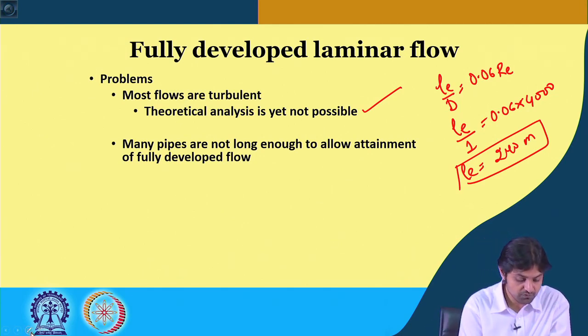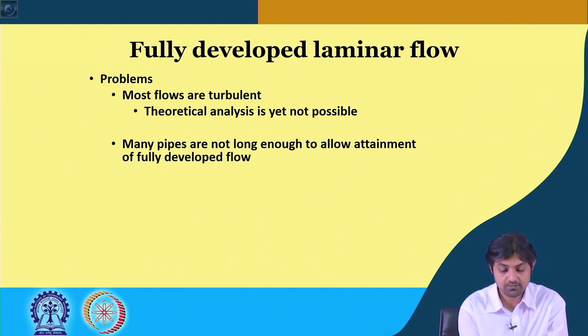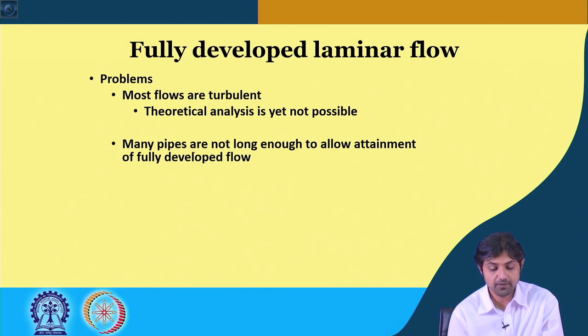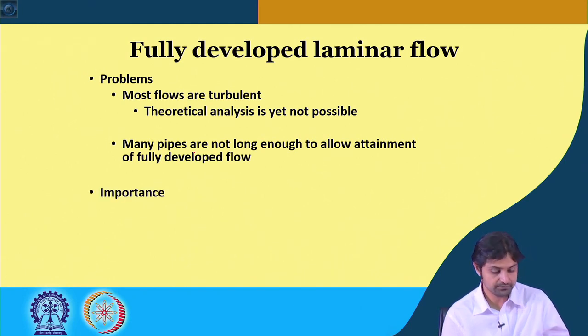So in most of the cases these pipes are not long enough to allow attainment of fully developed flow, because for that fully developed part we can actually do the real analysis, but that will occur only after the fully developed region has occurred, which in most cases does not, because the pipes are shorter in length.